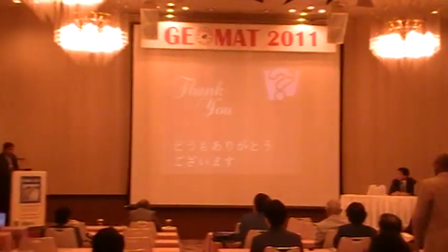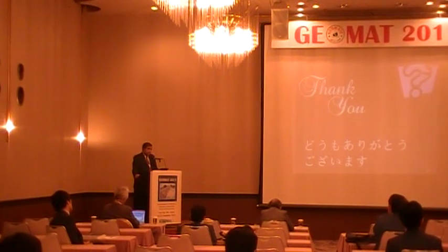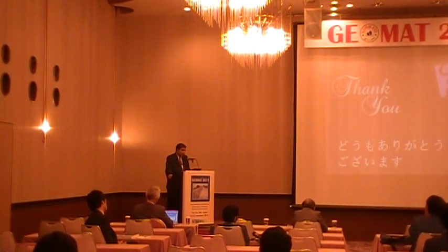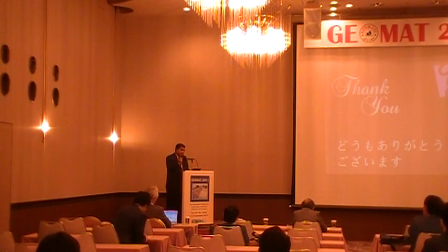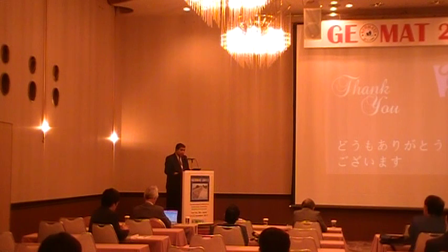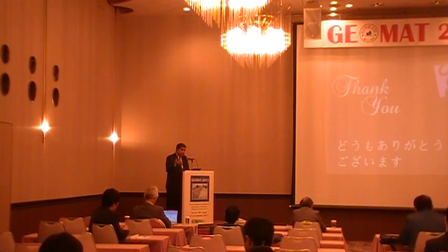It's a very interesting and practical question. Right now we have various instruments for measuring suction. In the low suction range, we can use tensiometers, and these tensiometers are capable of measuring suction from 0 to 100 kPa. There are also high capacity tensiometers, which are said to be HCT. Those also can be used, and they are a lot more expensive. And recently we have developed, and one paper has been published in ASTM, very recent one.